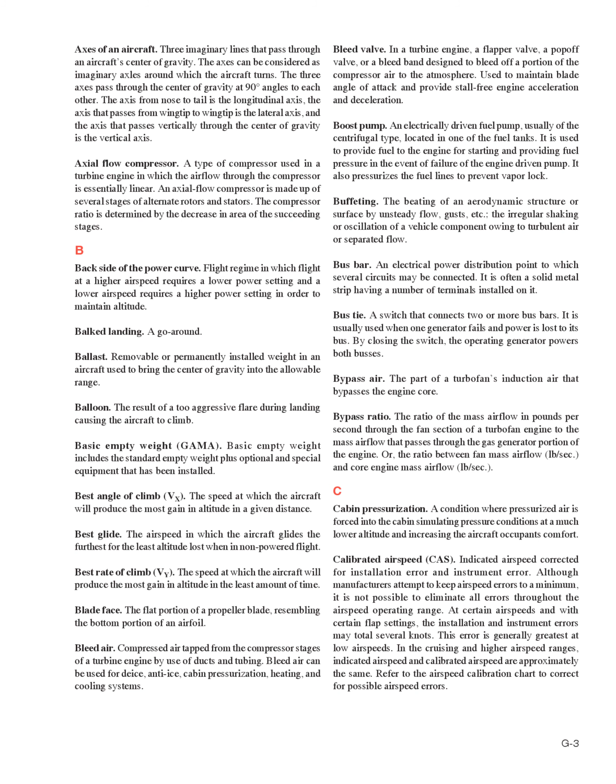Boost pump. An electrically driven fuel pump, usually of the centrifugal type, located in one of the fuel tanks. It is used to provide fuel to the engine for starting and providing fuel pressure in the event of failure of the engine-driven pump. It also pressurizes the fuel lines to prevent vapor lock.